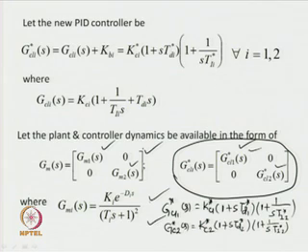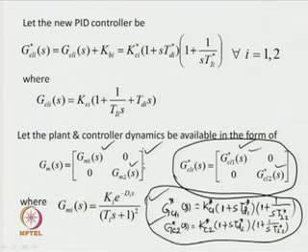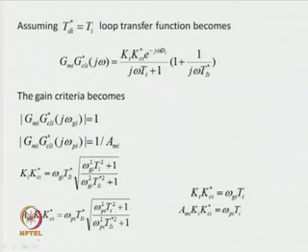With these forms of the new PID controllers, we shall now try to estimate the parameters of the controllers using phase and gain margin criteria. For that, for each loop in the analysis, let us assume that TDi star is equal to Ti.